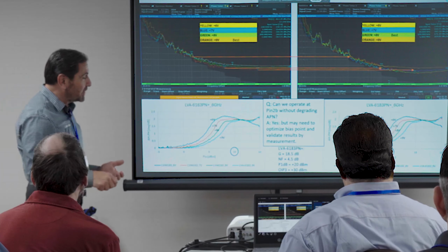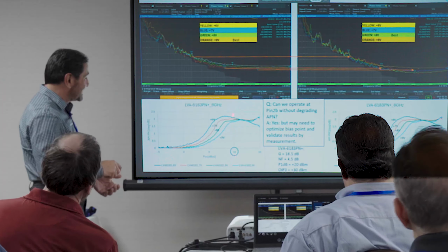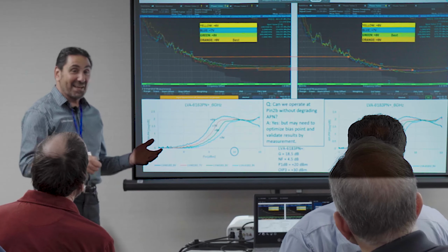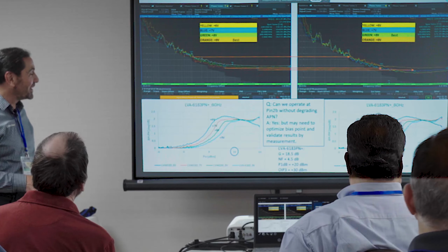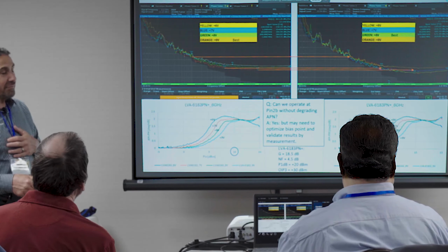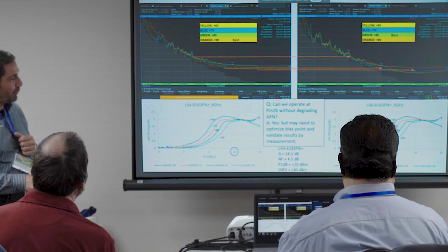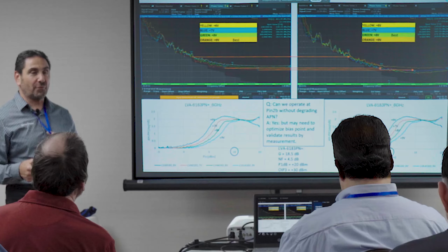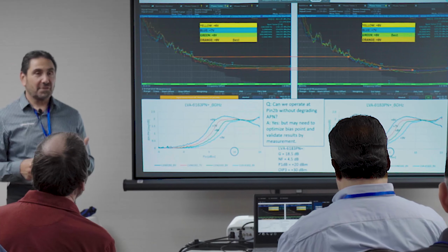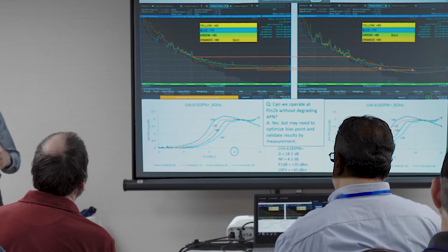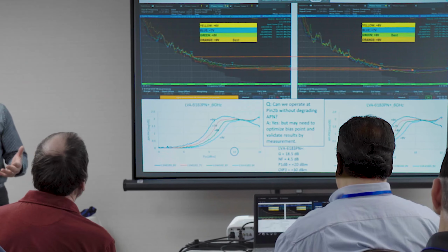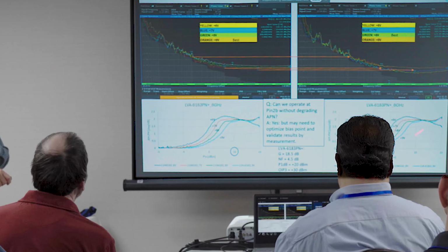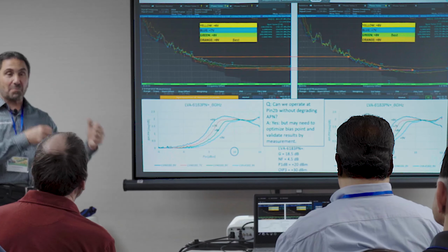All right, so we're going to look at +5 and we're going to look at +10. +5 is still very saturated. You know, we're not talking a little bit of compression here. But what you may have to do is change the device operating point, because look how the AM to PM curves all improve with increased device voltage. Is this general? Of course not. That would be too easy. So you have to really evaluate each part. Maybe you want to change the current a little bit, but know that there are ways to improve this, and that's when you want a test board.